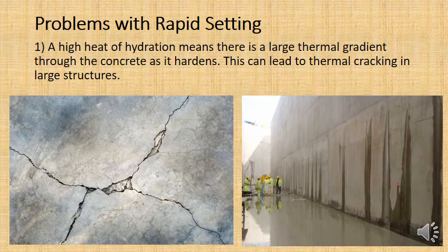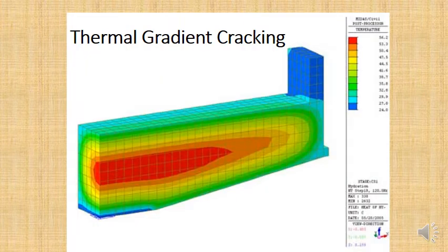But really deep inside the wall, a long way from the surface, cement will be reacting with water inside the concrete, and the heat from that reaction will not be able to escape quickly because it's deep in the very heart of the concrete.